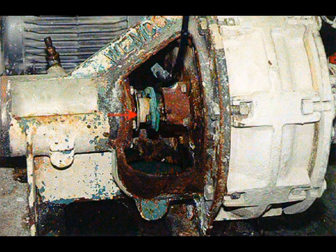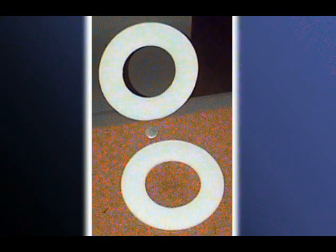It is important because it protects the bearings. The slinger ring is located on the shaft just behind the packing area, as shown in this picture. The slinger ring prevents water from migrating up the shaft to the bearing by throwing the water out away from the shaft. The slinger is made of metal or rubber. Actually, a slinger ring could be made easily from a piece of thick rubber.